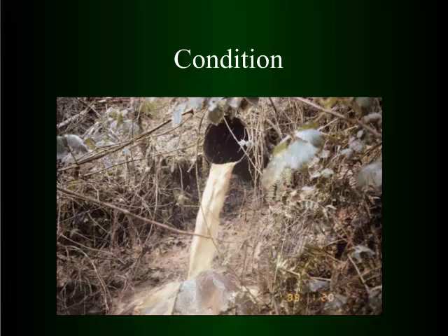This one's not functioning quite as well. We refer to these as shotgun pipes. You can see there's a pretty good plunge here. It's eroding. You can see mud. It looks like it's got a rock here. If they armored this, it might help, but that's too high of a plunge, too much energy hitting the ground. It's definitely causing erosion. What do you do?